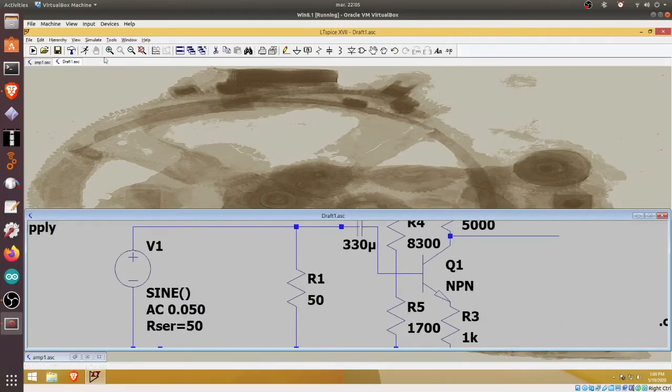Okay, so anyway, this was useful to show that you can use simulation to see what's going on. If I measure here, I can see correctly 1.7 volts in the bottom left part. You see? This is what I was expecting because this resistor is determining the value, as it's a voltage divider. And here, instead, I'm reading 414 millivolts. How is it possible if these are connected? Well, the answer is that these are probably not connected, for whatever reason.